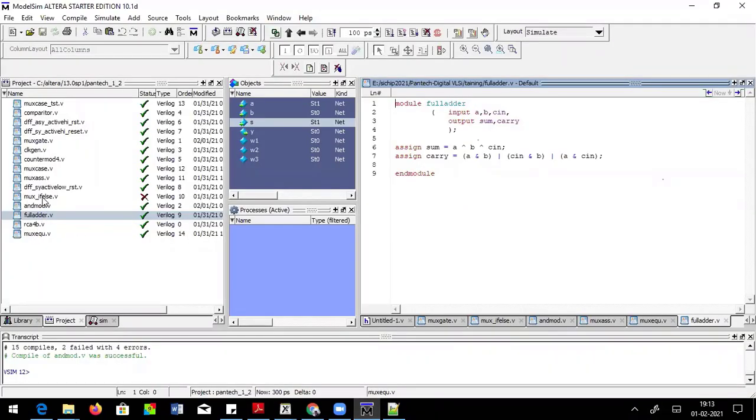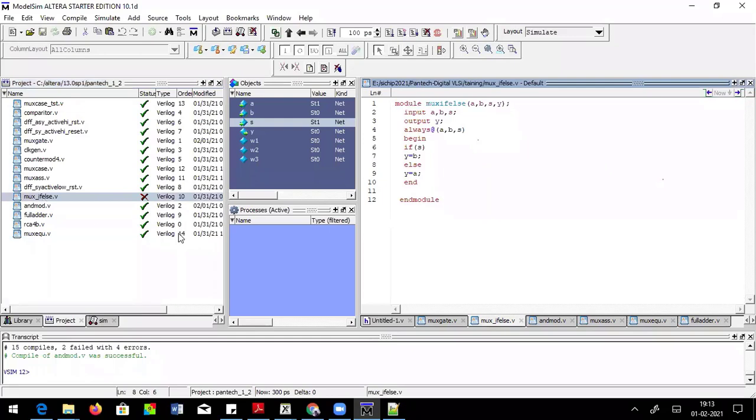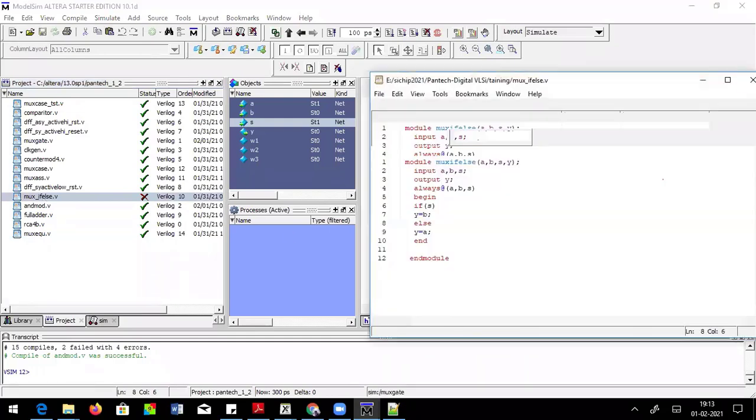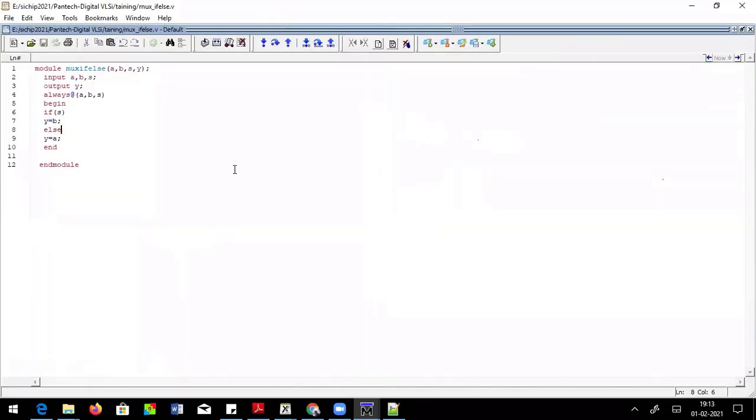So we have made mux using if-else statement. Now, can you just let me unlock it so that it becomes easy for you to see. Yeah, tell me what is the mistake here. The output should be at the first, sir. The inputs are available under first, I mean in the function mux if else. Output should be reg. Correct. One minute. So anyway, while you say something, it is easy for me to correct.